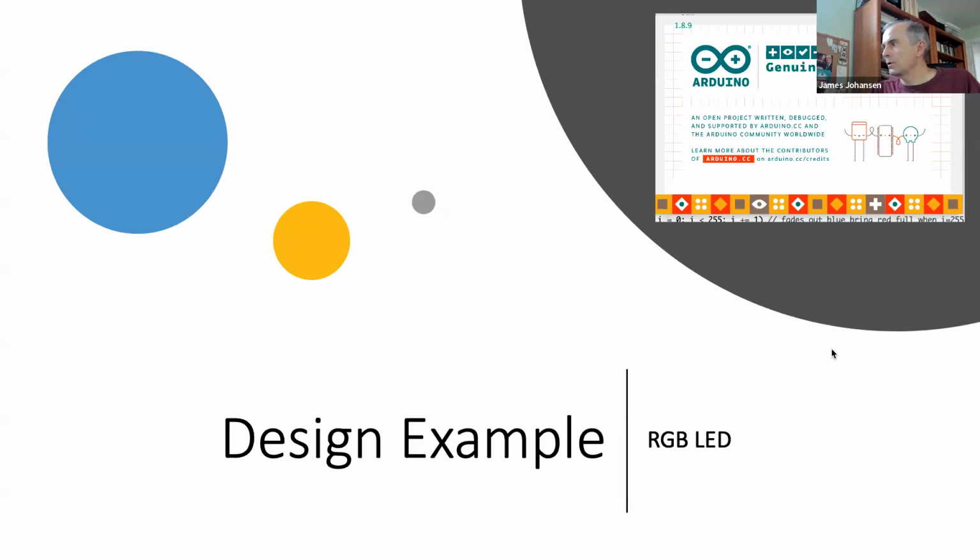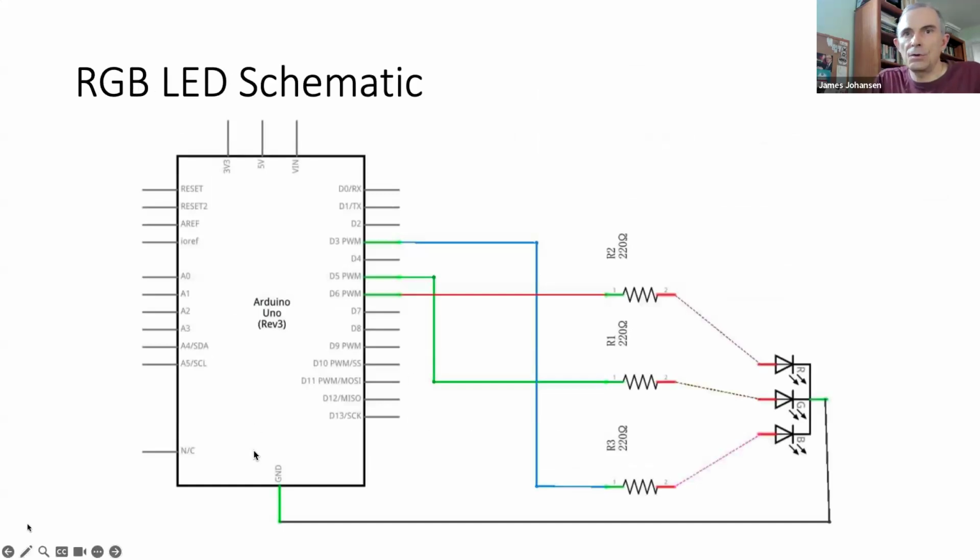So here are two ways of showing this design. For those that are engineers, this will look more familiar. This first thing here is the Arduino kit. These are specific pins that you're connecting things to. You have one wire here, this red wire, and you're going to put this on your breadboard. You stick a resistor in, and then you hook this up to an LED, and this has to go back to ground. When you power something up, you have to have where the voltage is, and then the other end goes to ground. That's how you're able to close the circuit.